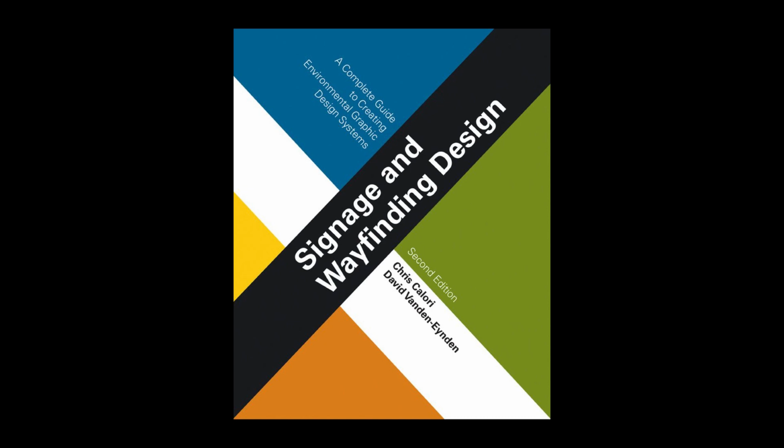Depending on the sign program's design, more or less detailed information may be required than indicated on this checklist. For example, if a sign is a simple flat square wall plaque, top and side views may not be required, since the thickness of the plaque can be conveyed by a callout rather than dimensioned on a side or top view. Similarly, if that plaque is simply glued to the wall, that can be called out as a note rather than shown in a side or top view.